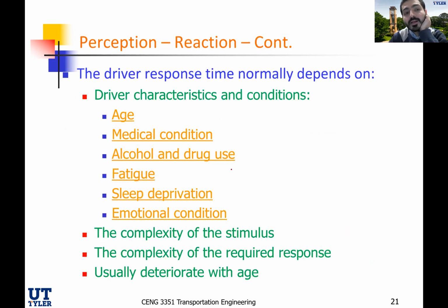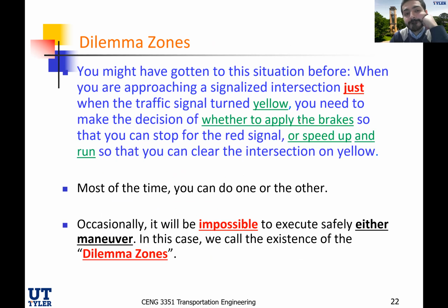I can ask you also, what are the driver characteristics and conditions that can contribute to increasing their reaction time? So I can ask you, give me 3 or 4 of those 6 of them. So age, medical condition, alcohol use, fatigue, sleep deprivation, all the way to the emotional condition.